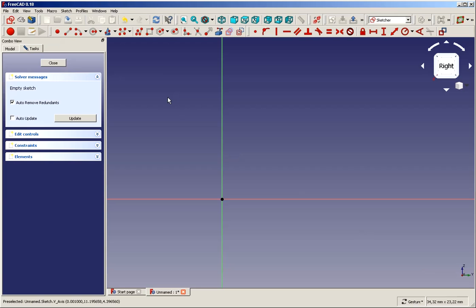The geometrical figure that we're going to use is a polyline, which is a line assembled of several individual straight lines, and I'm going to try to do this with auto constraining. With auto constraining, you can see the moment I touch the center line, a little symbol comes up right next to the cursor showing me this will be a point on object constraint.